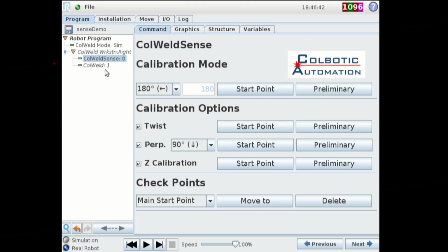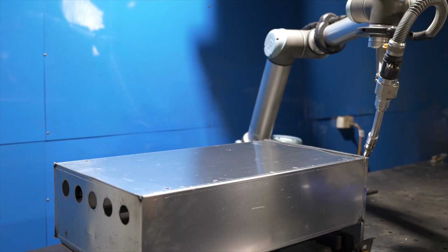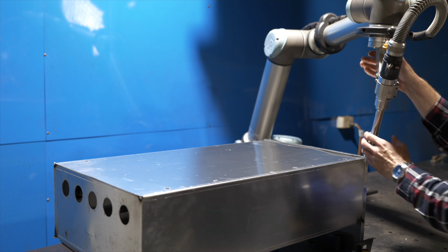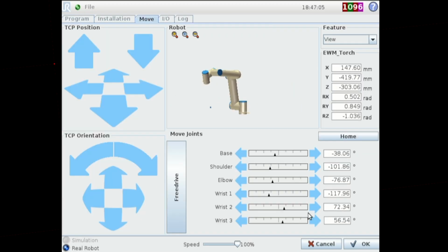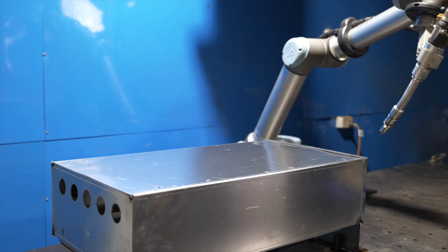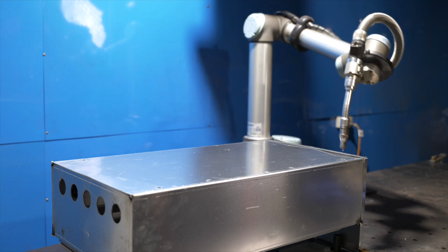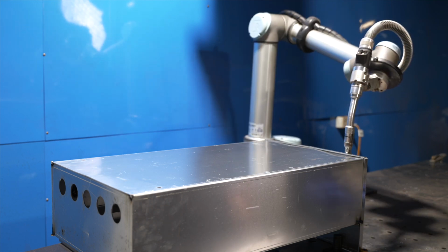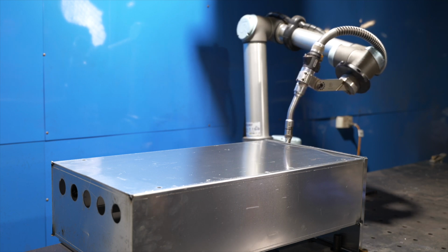We put our first point in, add our second point. We are now ready to run the software, and in the first time it runs through, it will be running in calibration mode. Calibration mode is very important because you're measuring the base part. All the subsequent parts are referenced relative to this.